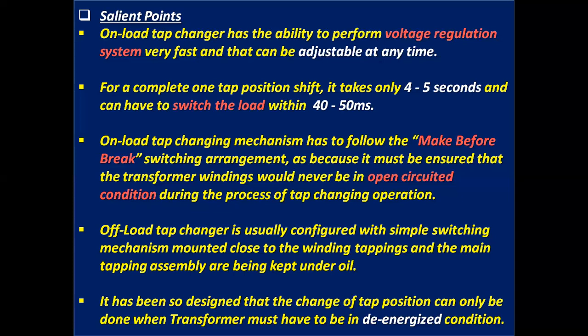On-load tap changing mechanism has to follow the make before break switching arrangement, because it must be ensured that the transformer winding would never be in open circuited condition during the process of tap changing operation.